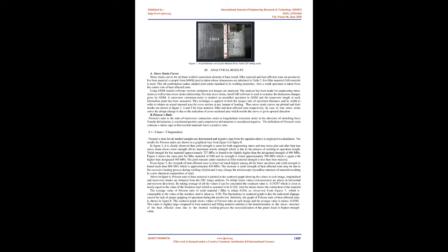Local strain analysis using the DIC technique requires the test specimen surface to be painted with a pattern. For this, it is sprinkled with white paint and black paint to ensure good contrast. Optionally, any paint can be used. The given sets of data, or images, are imported into GOM Correlate for DIC analysis.